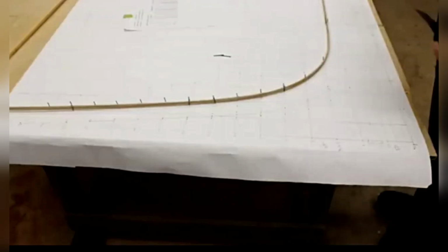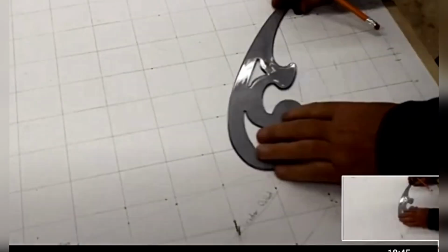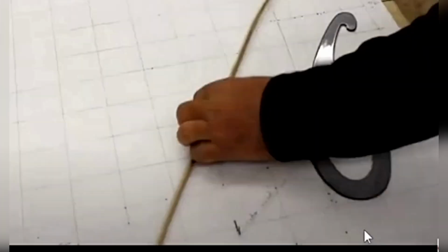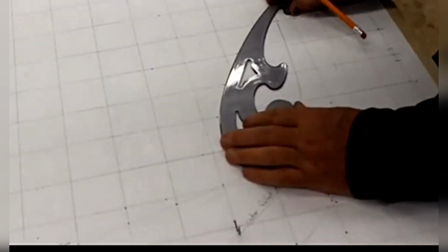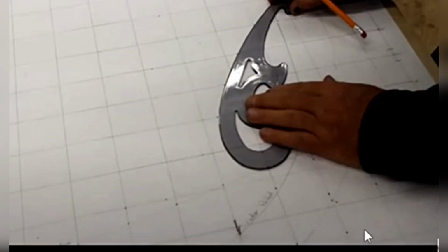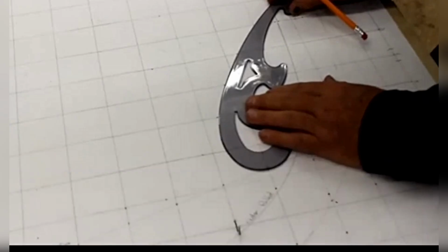And so, continuing on with the outer rabbet line from the keel through, first draft of my body plan. These curves are a little bit tight to be running a batten through in an S. So we're going to do our best to join up as many points as we can, and this is where the French curve starts to become your friend.